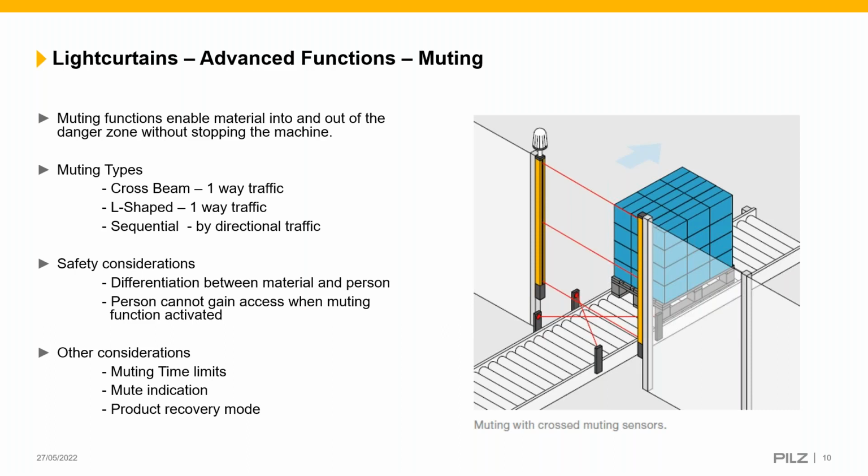If you deem this as foreseeable, then maybe you could look down the route of some of the advanced light curtains. The ones we offer enable you to mute just a set amount of beams. So you could leave so many at the top still live, meaning that anything outside of the pallet shape or pallet height would not make its way into the danger zone.